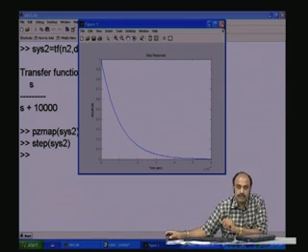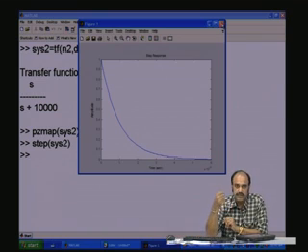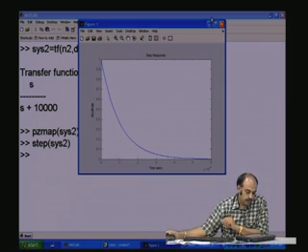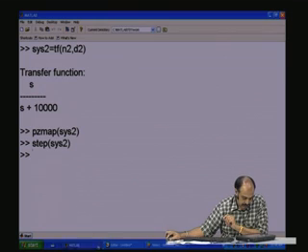They can be defined only for one input, one output. The numerator is a VI or a VS or a VR or any other parameter or a current, and the denominator is another variable. You cannot have multiple outputs, you have to look at them separately. But in the case of the state equation, I can have multiple inputs, multiple outputs, you can look at many outputs simultaneously. So, let us see simultaneously both the outputs.